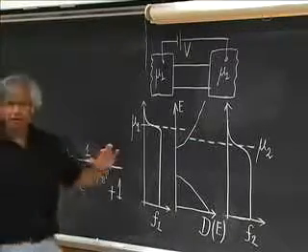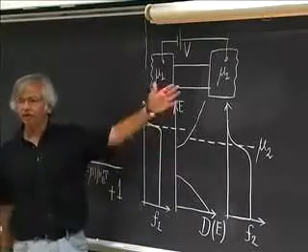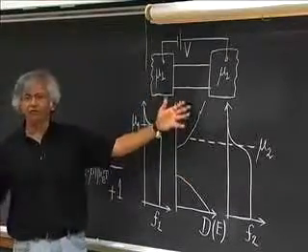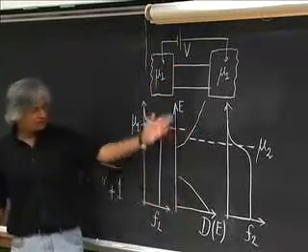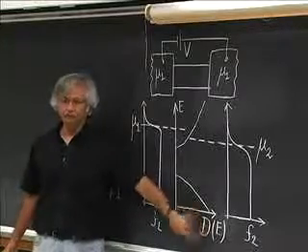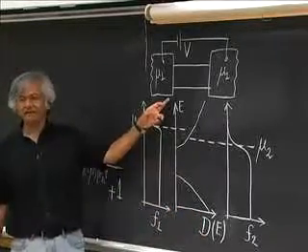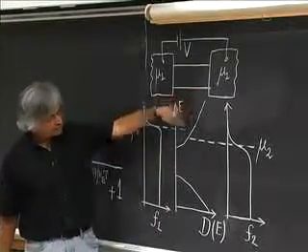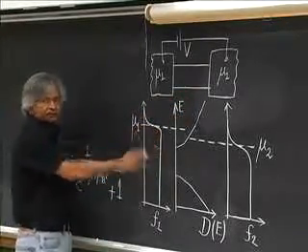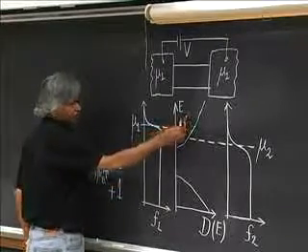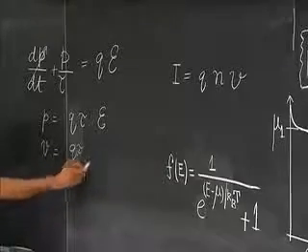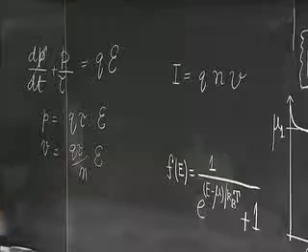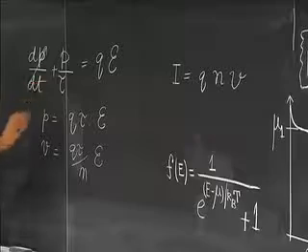And one of the first things, as you know, you should do is try to draw what you might call an energy level diagram, something that tells you where the allowed energy levels are inside this channel. What I've sketched here is some general density of states, D of E. This axis is energy, and it tells you the density of states, and I've sketched some generic density of states. So typically you have some non-zero value up to here, then you might have a band gap of sorts.